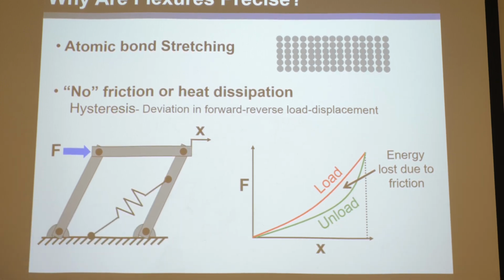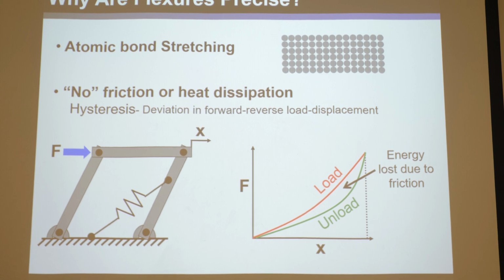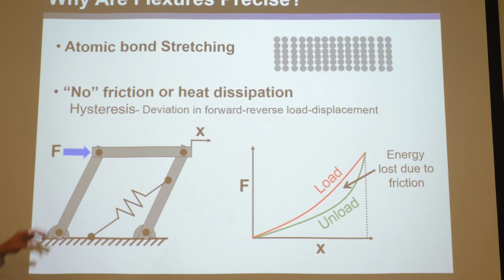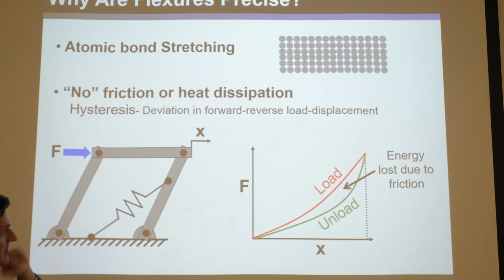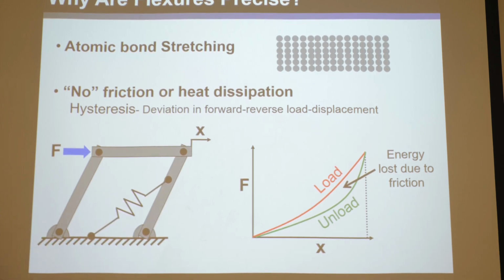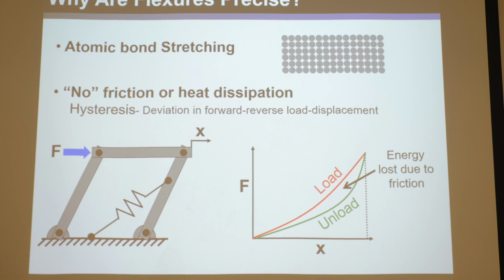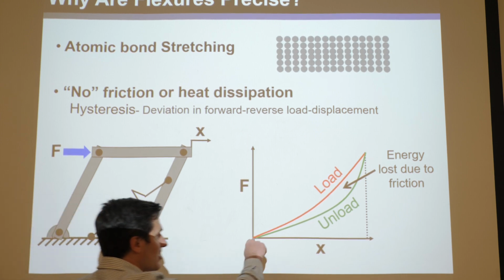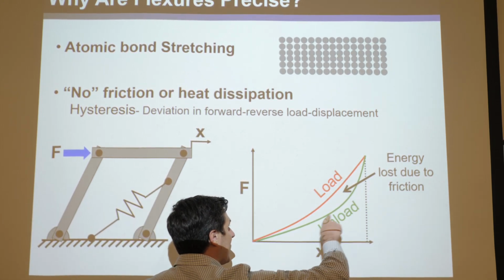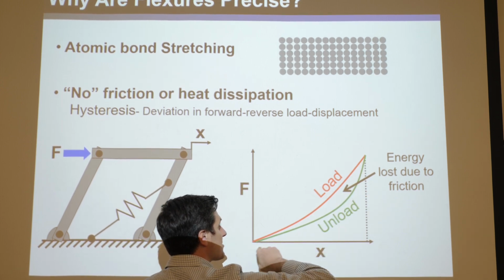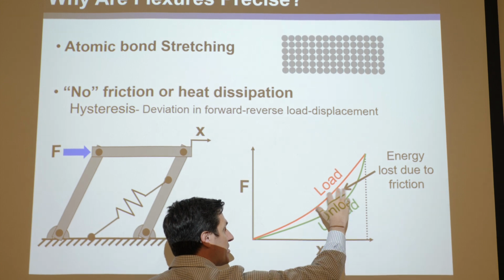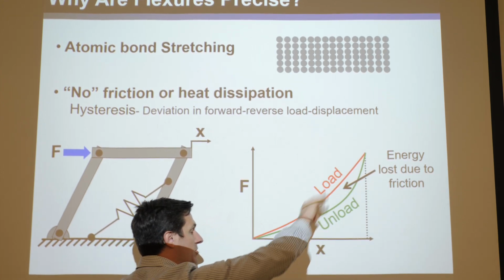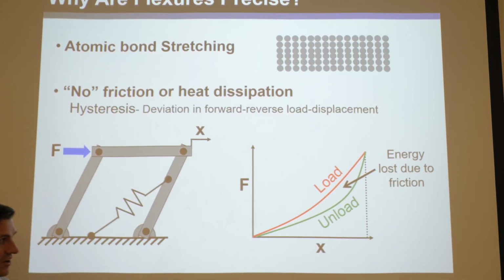The reason they're not on top of each other is because there's a lot of friction, there's a lot of energy lost and dissipated at the rigid joints, okay, through sliding contact. So it generates friction, and that energy has to go somewhere. And that energy that's dissipated is the area in this little sliver. It's called a hysteresis loop, right? So the total energy recovered from strain energy plus that dissipated energy is the work you put in, okay?